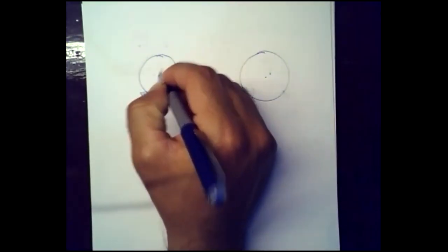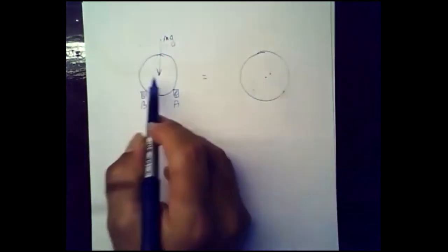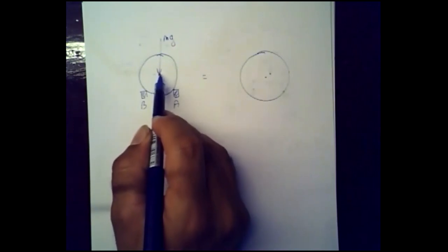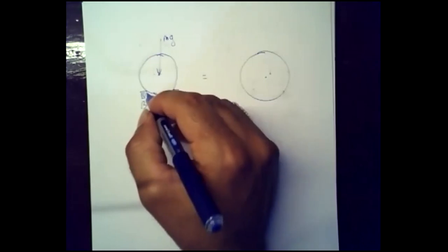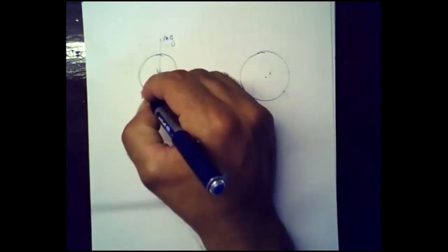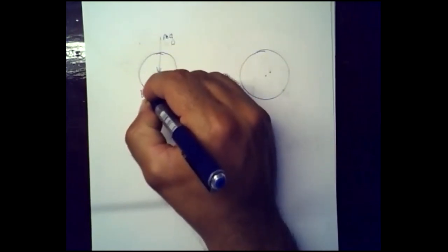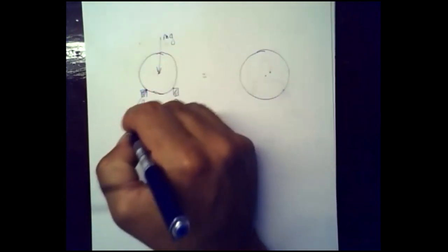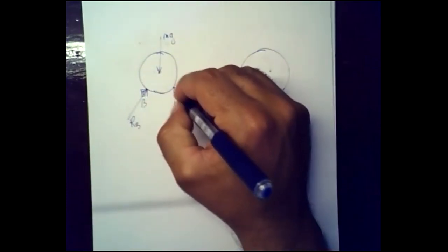The first step is we're going to draw the free body diagram, and the weight will be at the centroid, or the center of gravity of the spool. Sometimes you actually put the weight in the air, because the center of gravity doesn't have to actually be on the material. How about the reactions at A and B? The reaction at B is always going to be perpendicular to the tangent, and the perpendicular to a tangent on a circle will always be pointing toward the center. So that is your RB. And RA we're going to assume to be 0.